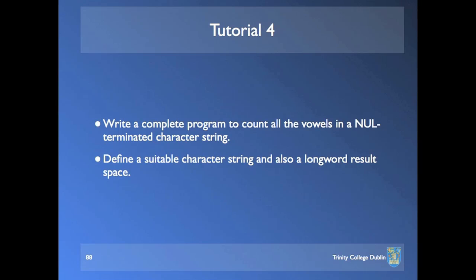And also, okay, now, this instruction here is add, just like the first add there, it does not make use of the X bit. Maybe that answers your question, I don't know. It does not look back at the outcome of this calculation here, because it's just a straightforward add, it's not add extend. So it will be a generator of an X bit and a C bit, but it won't consume it. It isn't taking it into account.